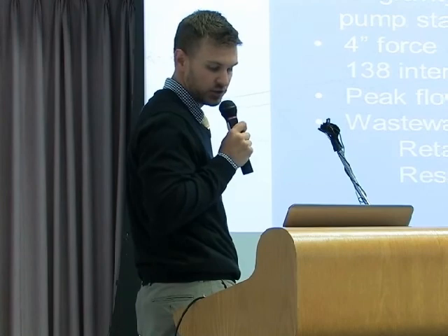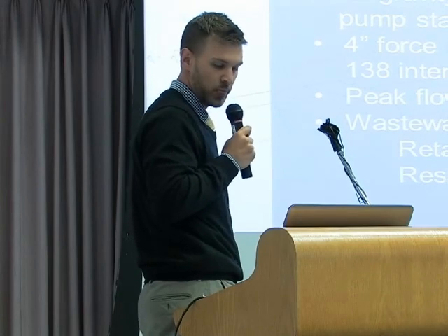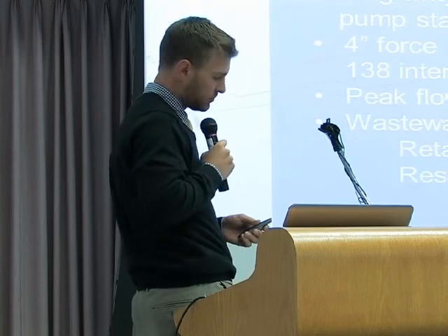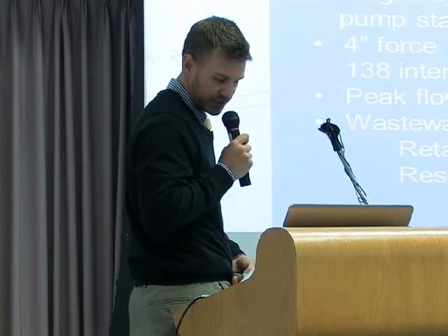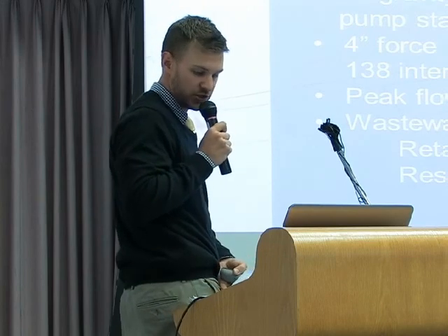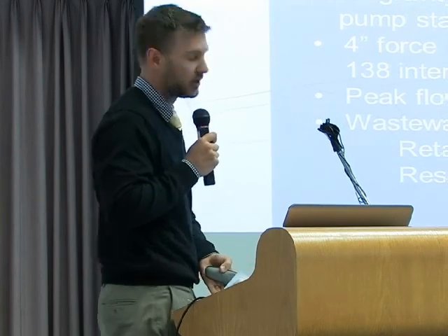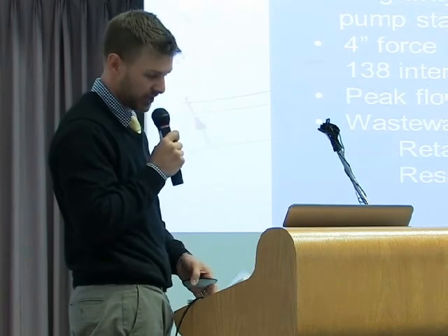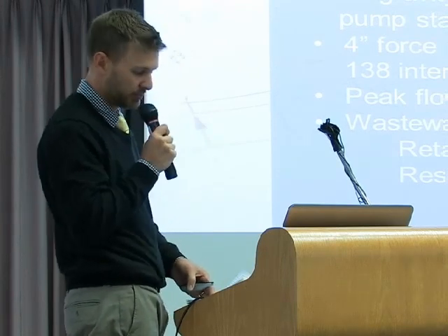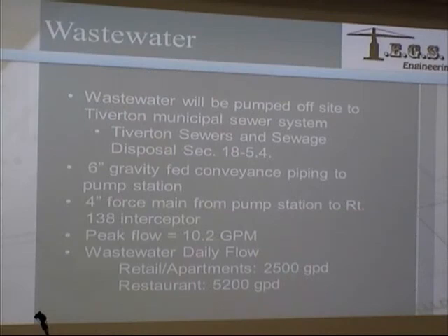Wastewater. All wastewater will be pumped off-site to the Tiverton Municipal Sewer System, tying in at the Route 138 and Sousa Road interceptor. The wastewater daily design flows of 5,200 gallons per day from the restaurant and 2,500 gallons per day from the retail residential will travel to a pump station via 6-inch gravity-fed pipes and be pumped uphill via a 4-inch main.